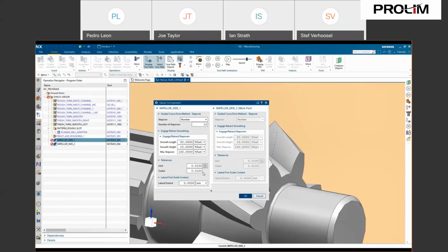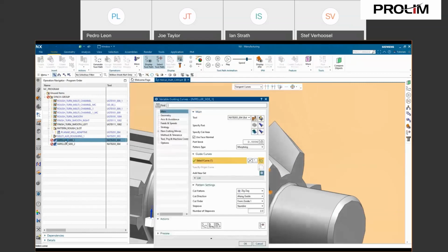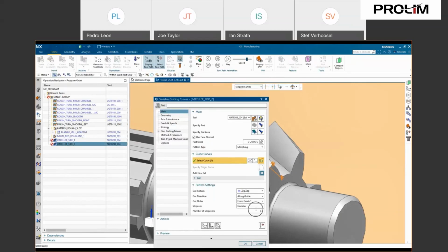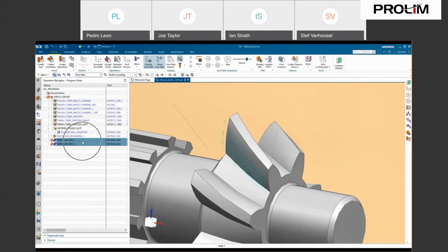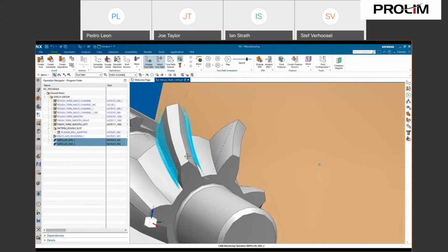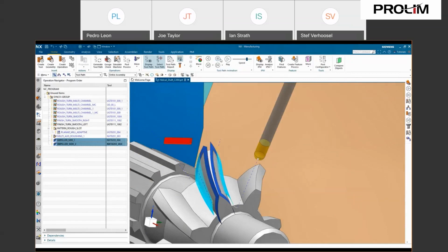Very useful if you manage and create new templates based on older templates and just want to match all the new functionalities in there. Just to show you that it's all matched up. It's side 1 and side 2, they're completely the same now. Just generate them and you will see that the toolpath will be exactly the same. And so on the left flank, right flank, you can see that it's completely the same. And of course the replay button, which is very helpful to quickly see what the tool is doing.